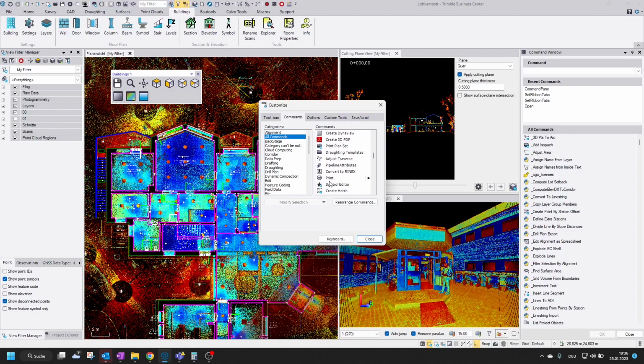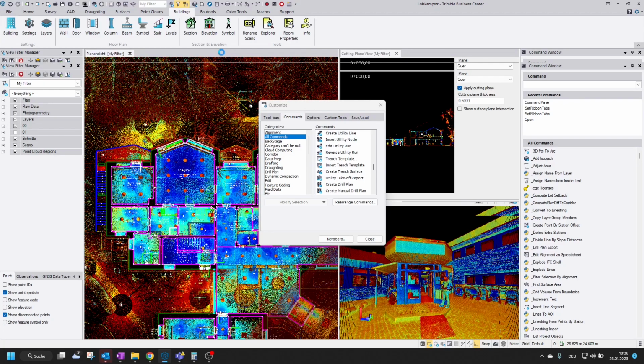And then the next thing that I would use for my point clouds, for changing very quickly between the views that I want to see, is no shading, normal shading, and ambient shading. And a very useful function is see all, see inside, and see outline, if you have the scanning module. If not, these functions will not be available. And then after that we can use whatever we want, but for example, let's keep this one. I just put it here, fix.